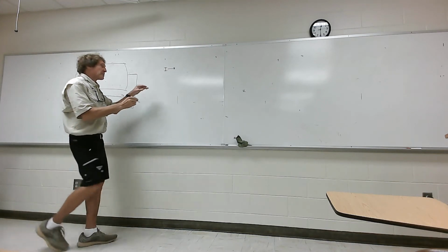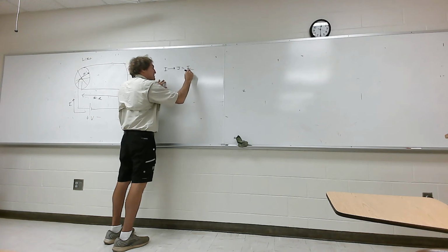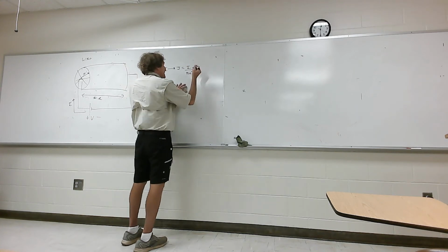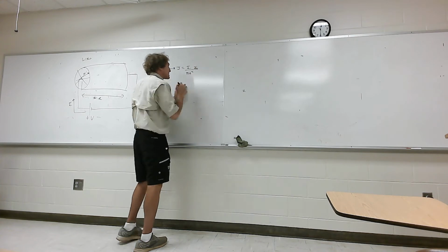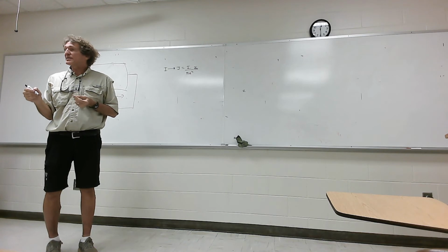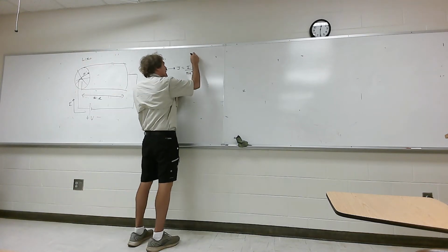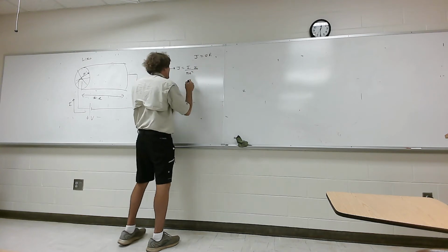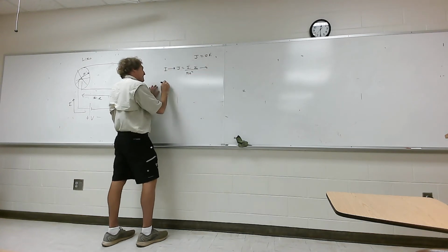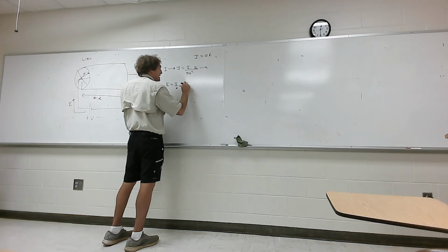Then you say it's equally distributed over the cross-sectional area, so you get J, which is nothing more than I over pi a squared if it's a circular wire. You can say it's in the AZ direction, but that's not really important. Y'all follow me? You remember the next step? After you get J, what do you do? E, right? J is equal to sigma E. So now I get E. My value of E is J over sigma, which is I over pi a squared times sigma.